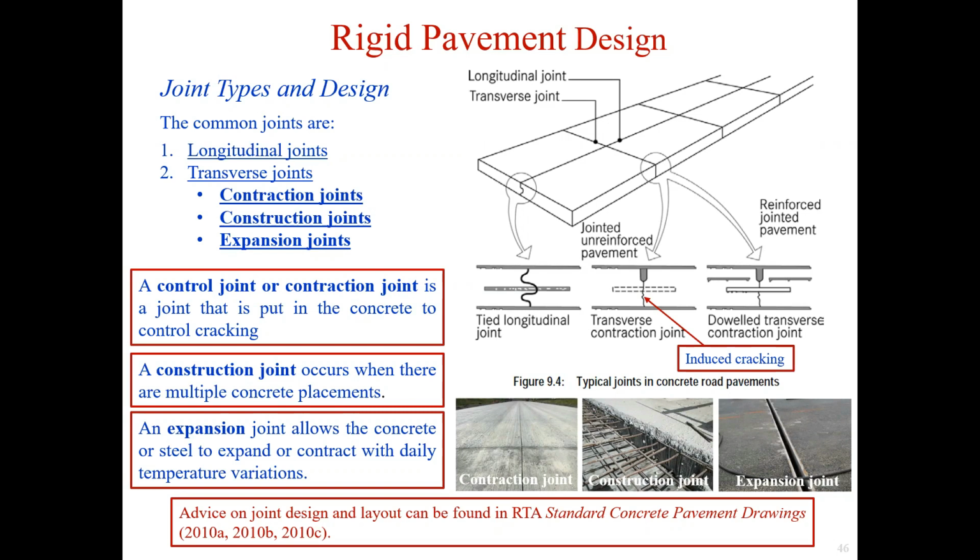The objectives of joint design are to develop a jointing system which will control transverse and longitudinal cracking and provide adequate load transfer across joints, so the pavement will have adequate riding qualities over its service life. Joints normally should be selected to minimize the intrusion of water and incompressible solids. This figure illustrates various joint types.